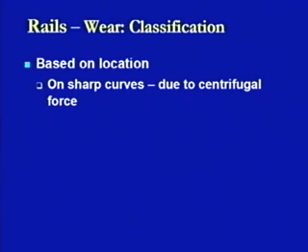Therefore, what will happen is the three types of actions we have discussed previously: the slipping, the skidding and the striking of the wheel. All three things will be happening. Now, the slipping and skidding will happen at the top surface of the rail head, and therefore may cause wearing at the top surface of the rail head, whereas the striking of the wheel, because of the flanges hitting the rail section, will be at the side of the rail head. Therefore, in this case the wearing will be on the side of the rail head.